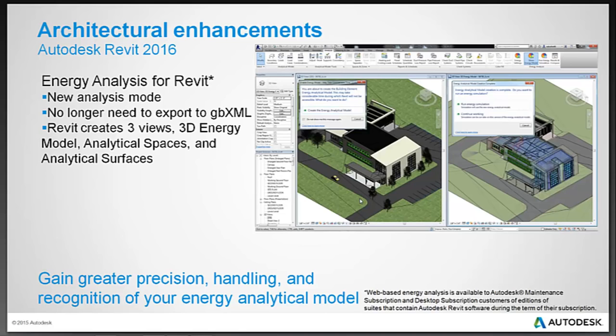And then in the results and compare window, the energy cost range dashboard provides new analysis tools. You're going to use this dashboard to help understand the current energy cost of the analyzed building model and how changes to identified variables can help reduce the overall cost. And then finally, the potential energy savings chart has been removed from the energy analysis results.